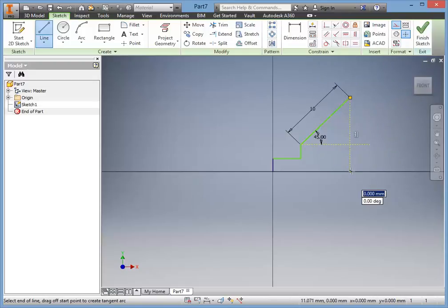Click once, and you'll notice that the guide line, the construction line, is a bright yellow dotted line. Now these lines are handy because they're not visible in your final product. They are used to match up other items that you might use in your drawing though.